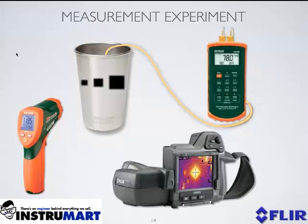Now, from our previous webinar titled Thermocouple Measurements versus IR Camera Measurements, we learned that bead wire thermocouples do a good job of reporting temperatures of gases and fluids. As such, the thermocouple will be a good indicator of what my cup internal temperature is and a very close indicator of what my cup surface target temperature should be. So it's a good baseline for me to compare these other measurement devices against. So I'm going to do that. I'm going to take multiple measurements of my electrical tape targets that have a known emissivity value with the IR thermometer and IR camera, and I'm going to compare the results.